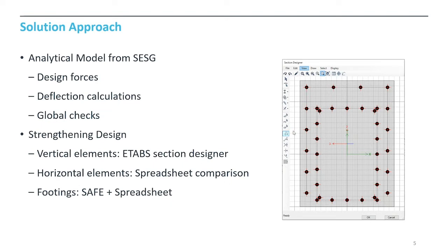For instance, this column was eccentric in its final execution because a side ramp was there, so it was not possible to extend the column on this side. We modeled exactly what we wanted with the position of rebars, put this section into ETABS, and could get the demand to capacity ratio directly.